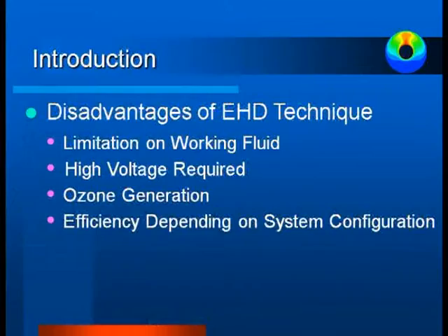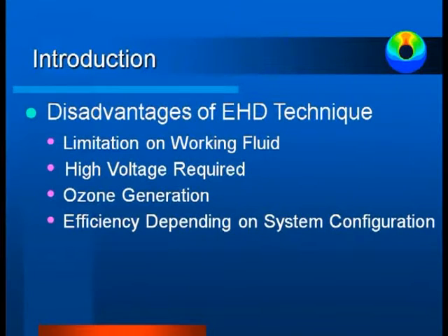Air will be good, or gases will be good. And if we want to apply a liquid, it has to be, for example, transformer oil, something that cannot conduct electricity. And it requires high voltage, but we can relax this requirement because, as I mentioned, it really depends on the spacing. If the spacing is reduced, then the high voltage requirement can be relaxed.